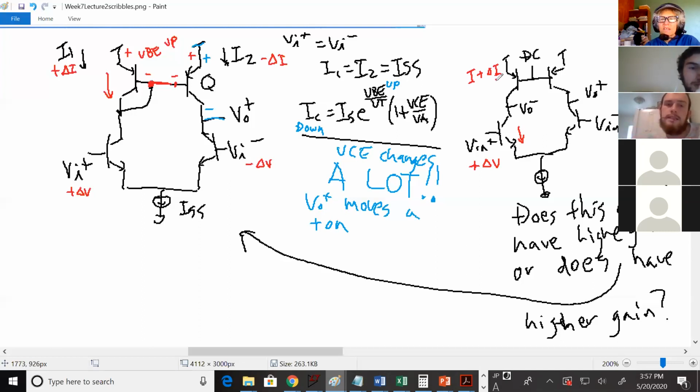So in this case, I guess properly I should say the magnitude. I'm giving you bad habits here by just dropping signs randomly. But yeah, VCE goes up. Does the base voltage change? No, because it's externally biased. It's DC. So now the VBE on this side doesn't change.